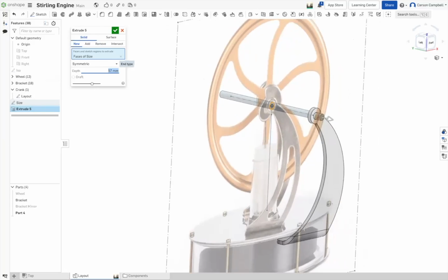The other way to do this is to go with a 4mm, have a shoulder on it, and put a nut on it. And if you're going to put a nut on the outside of this thing, you'll want to put 2 nuts. So one nut jams up against the other one, and then the nuts never come loose. If you put one nut on, in 6 months, it'll come loose, right? So these are all the things that we should be considering at this point.